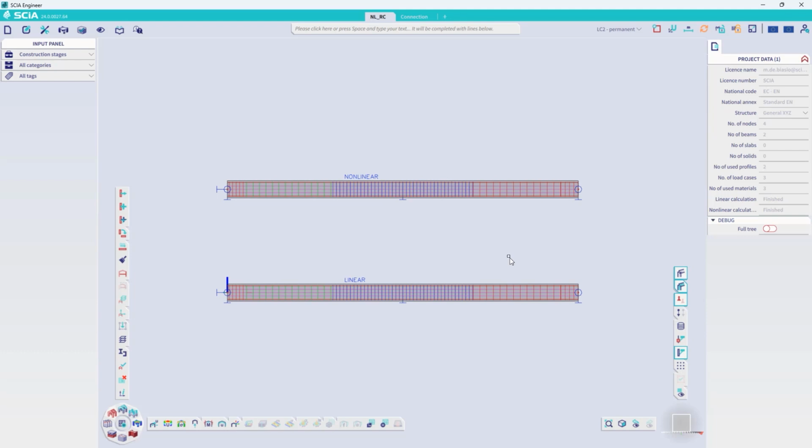And of course, I add that in order to have convergence of this law, you have to have reinforcement in the elements, because without reinforcement, the convergence is very difficult, because as soon as there is tension in the structure, there are no more elements able to carry the load. But if you have reinforcement, the effort is transmitted to the rebars, and so the convergence can be reached.